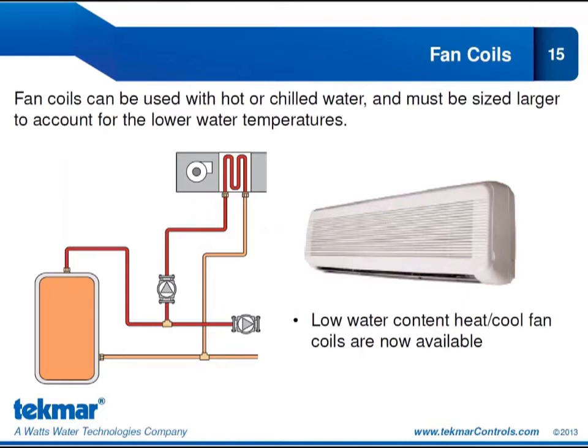But generally speaking, if you have an ordinary fan coil, then we have to size them larger to compensate for the lower supply temperature. Now, if we don't want to go with fan coils, what other options do we have for that second stage of heat?